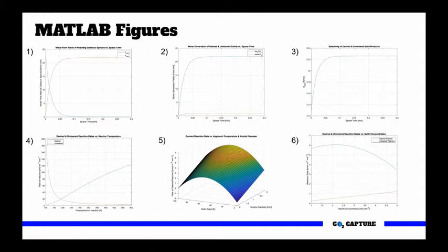The approach temperature parameter represents the temperature difference between the adiabatic saturation temperature of the syngas feed and the reactor itself. A peak can be seen in the approach temperature parameter, which was chosen to be the value used in the optimizations. In Figure 6, the concentration of aqueous sodium hydroxide was altered to find the values which corresponds to the maximum desired reaction rate.